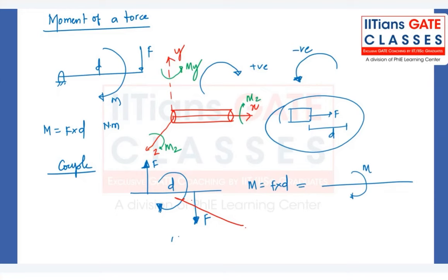We got one more question here, from Abhinav. How can there be a resultant moment out of a couple if a couple consists of two balanced, opposite direction forces? Yes, because they are separated by a certain distance d. If the two forces are at the same point, there is no moment. But if you start increasing the distance between them, you can clearly see a moment. Let's take a simple example.